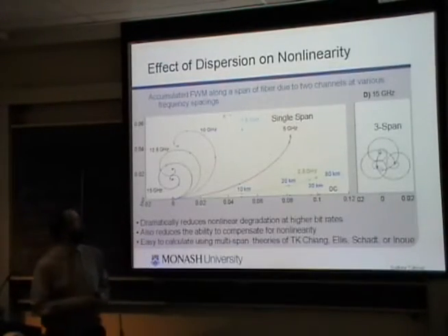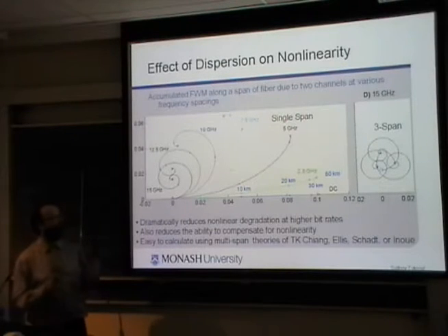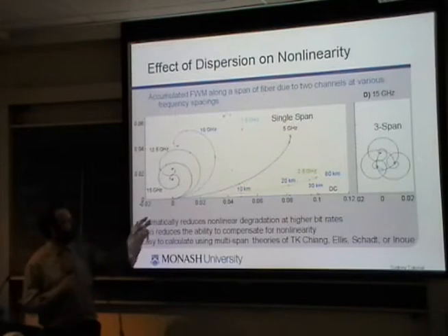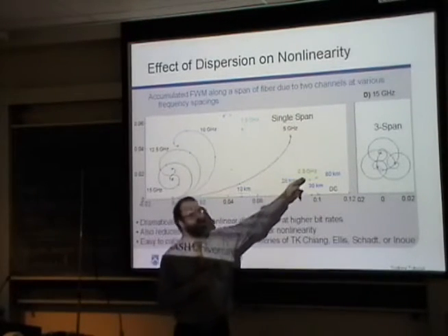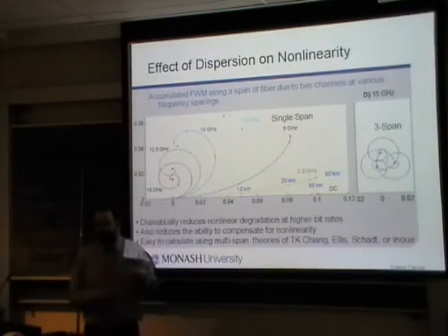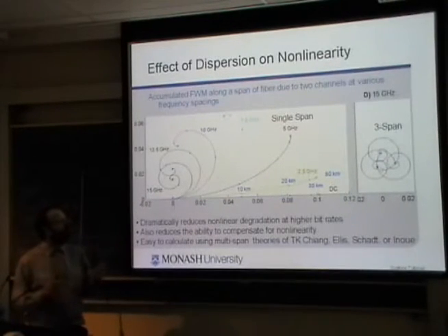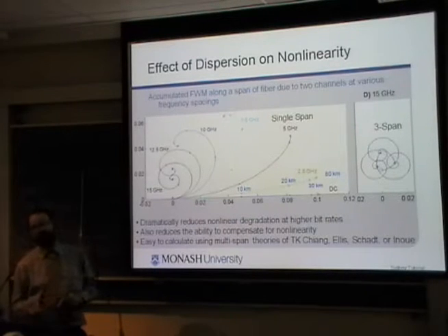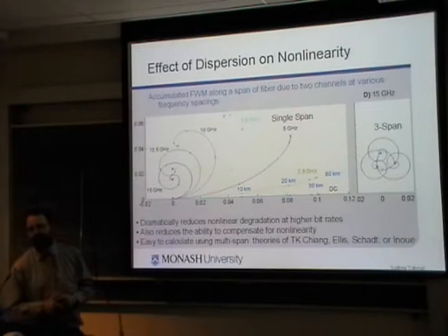That's the key diagram: if you look at four-wave mixing and how it accumulates along the fibre and treat it as little vectors, just summing up and changing phase every step, click, click, click, then you can get an idea of how certain frequency components build up in a link and eventually add in phase, or if you're lucky at some frequencies, cancel one another out. I hope that's really interesting.